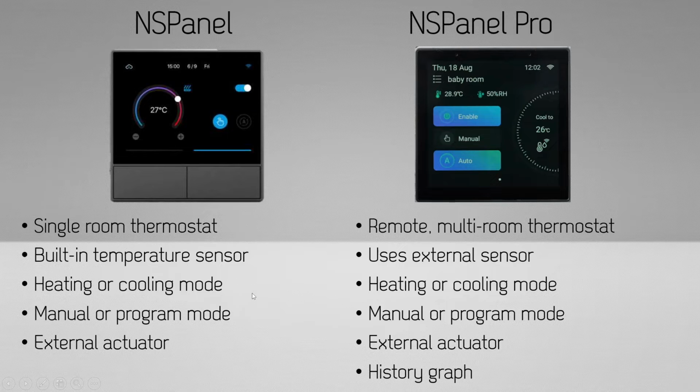So both of these devices support a heating or a cooling mode, which means that in heating mode, they turn on if the room temperature is less than the desired or the set temperature. In a cooling mode, it's the other way around. So both of them support that. Both of them have a manual mode or a program mode.